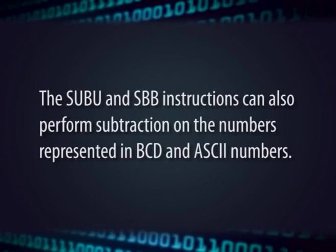In the earlier topic, the addition of BCD and ASCII numbers was explained using the DAA and AAA instructions. The SUB and SBB instructions can also perform subtraction on numbers represented in these formats. However, to bring the result into BCD and ASCII format, an adjustment in the result is needed.